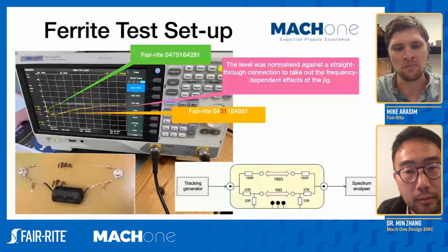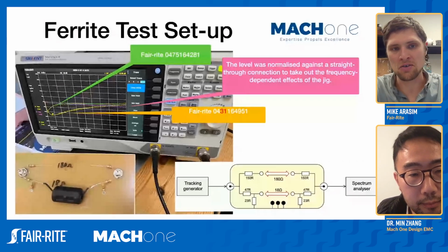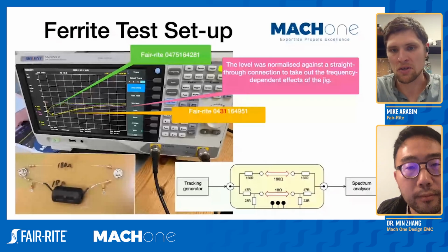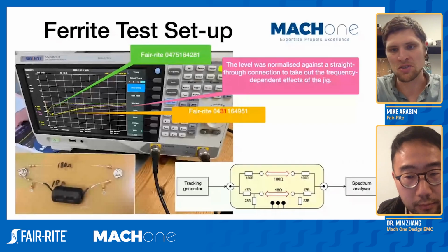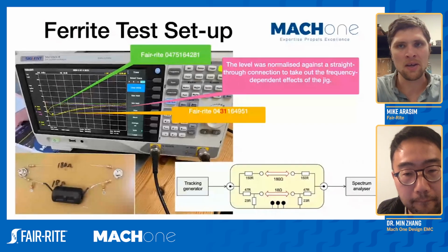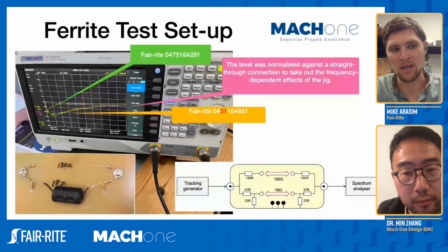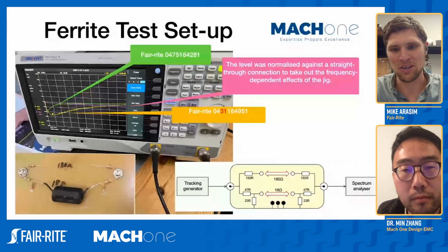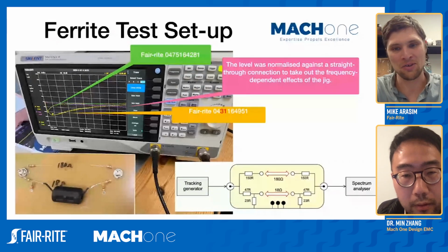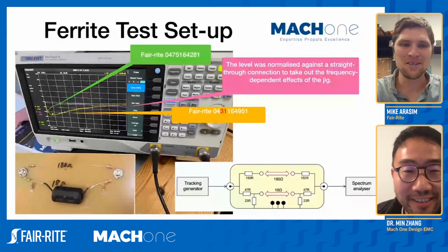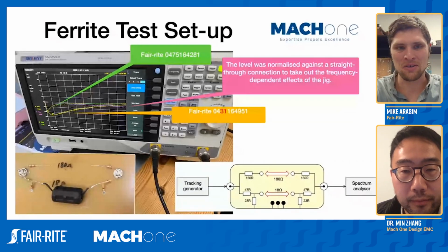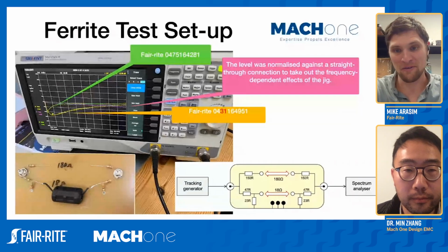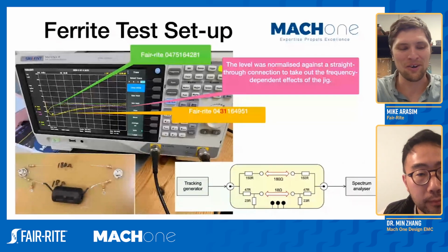This is the case here. And in terms of conductor, it's important that we keep the same conductor diameter consistent from part to part. And the wire length, we keep as short as we practically can, because ultimately you could put a pretty long piece of wire and it really looks like a pretty good ferrite when you're looking at it on an impedance analyzer. Exactly. So we try to minimize that to keep the measurement of the ferrite.